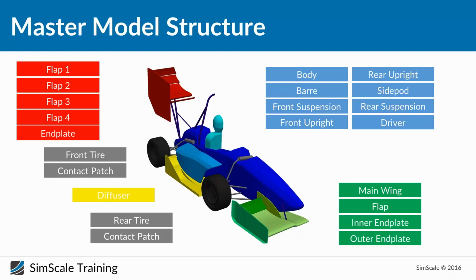Of course, here you have to know one thing. When you work with the STL, usually you will have one solid that will represent the whole geometry. And this can create some problems, especially later when you start to do post-processing or you want to refine in specific regions. Sometimes you can't get real control over a single part because your STL representation is one solid for the whole body.